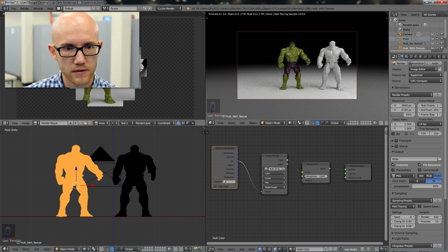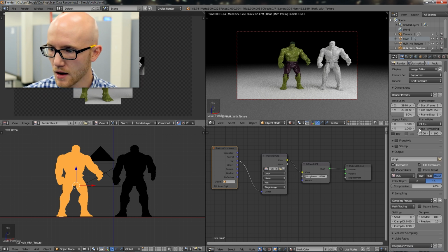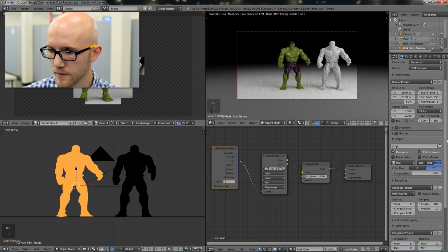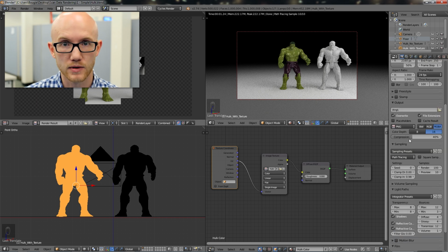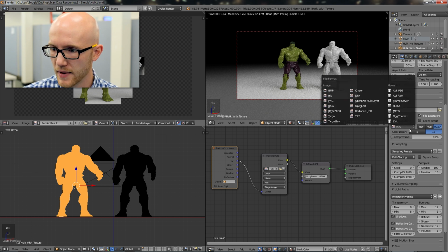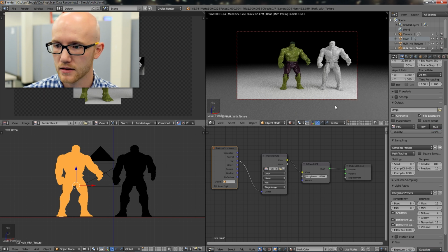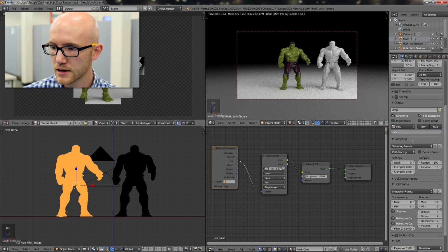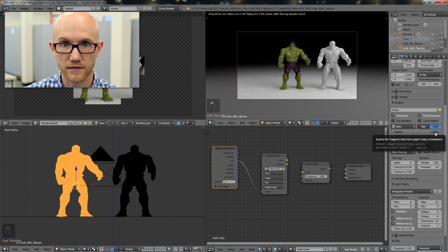And then when you're done rendering here, you can export as an actual JPEG or PNG image. I have this set to PNG right now. I'm actually going to change this for the files that I export. I'm going to set this to JPEG, quality to 100, and set it to RGB. These are the settings that the files I'm going to make available for download will have.